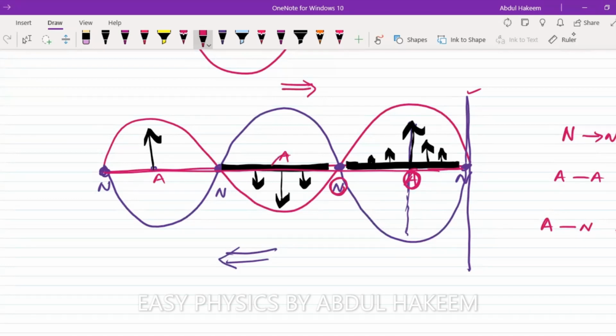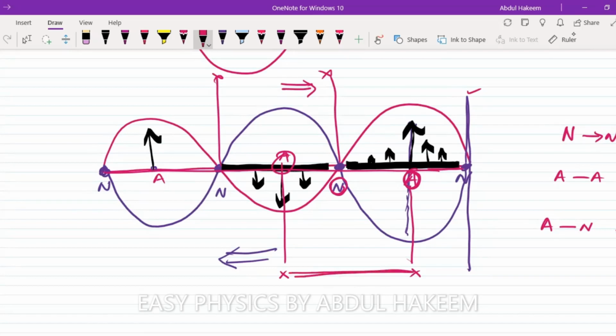And again here, the temperature will be maximum due to high intensity microwave, and the resistance will be low. If we mark two consecutive minimum resistance points, or two maximum resistance points, then measuring the distance between these 2 points, antinode to antinode, this is lambda by 2. So this distance is lambda by 2.